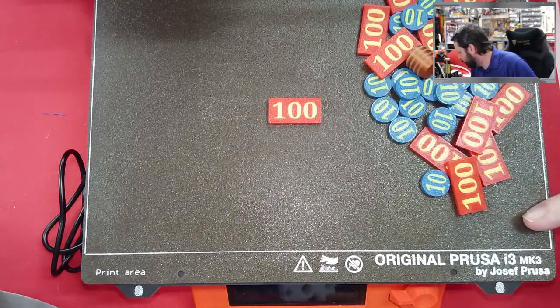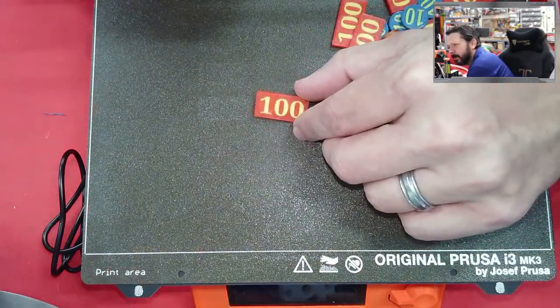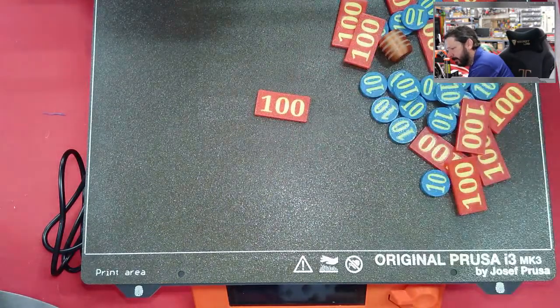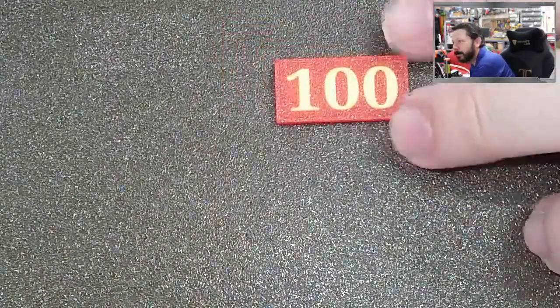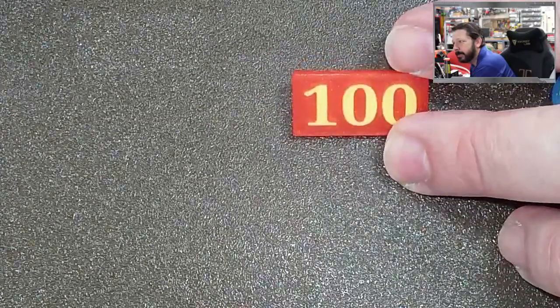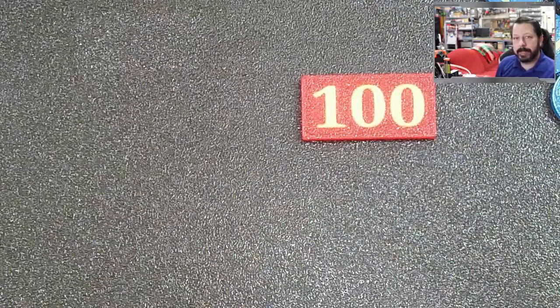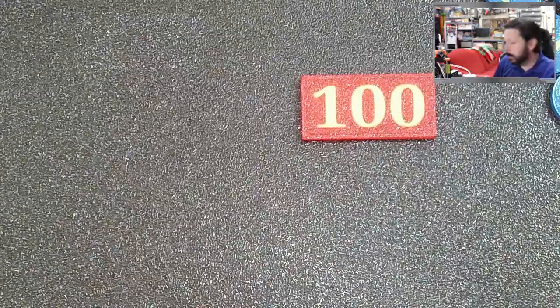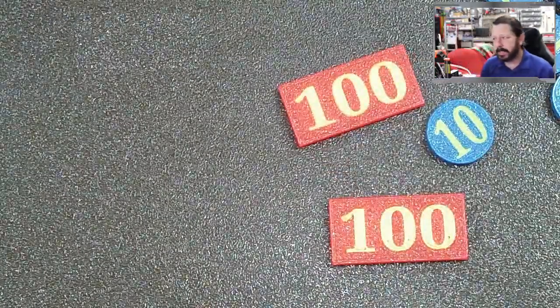So this is a PEI sheet, but the PEI has a little bit of a rough texture, and so that texture gets picked up. You can kind of tell it's in there. Maybe if I zoom in, yeah, you can see it there for sure. Those little sparkles are not sparkles; they're actually the texture. So it does create at least one surface, the surface that's on the print bed, as a really nice surface. You can't tell it's 3D printed. Now the other side still looks 3D printed. You could maybe turn on ironing or something like that to reduce some of the layer lines, but you do get one side that has a pretty nice finished texture on it.